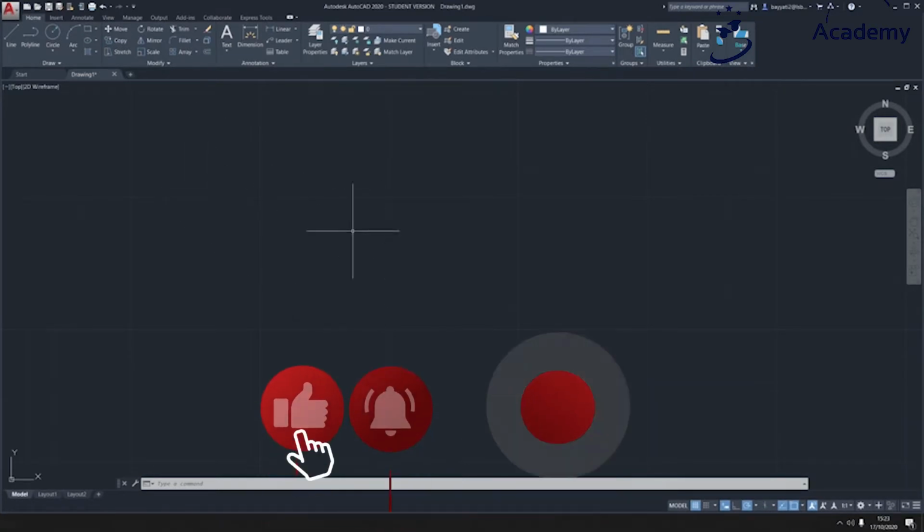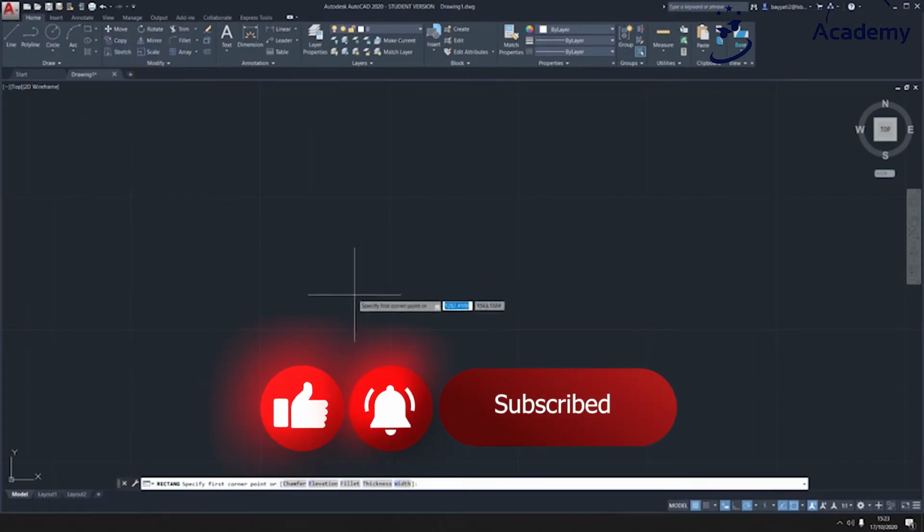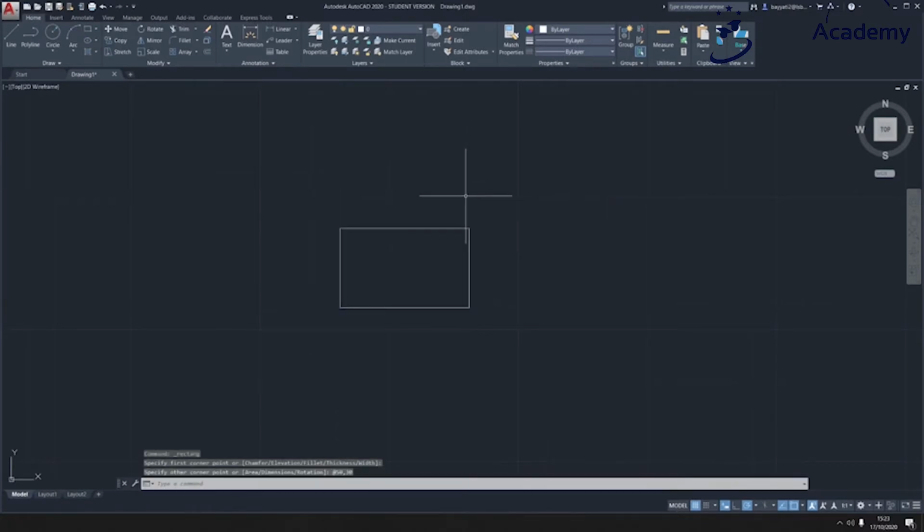And I'm going to demonstrate this using exercise 1 in the handout. So first, I'm going to draw the rectangle. I'll click anywhere in my drawing space after clicking the rectangle tool, and I'll type 50, 30. Then I will go to the circle tool, click on the snap point in the top right corner, then type the radius, which is 20.